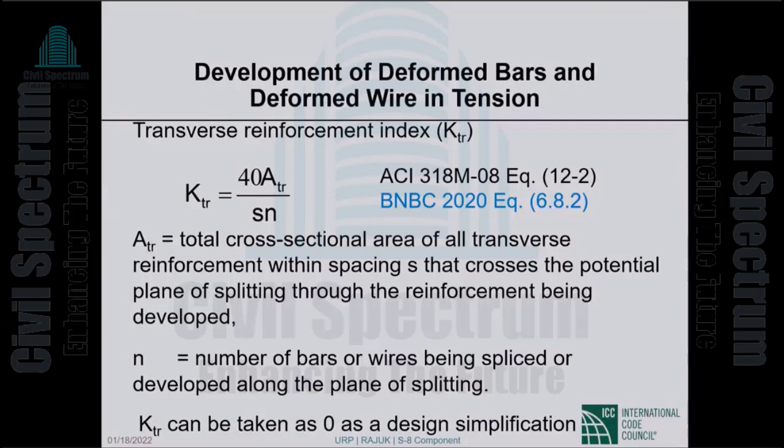A sub TR is total cross-sectional area of all transverse reinforcement within spacing S that crosses the potential plane of splitting through the reinforcement